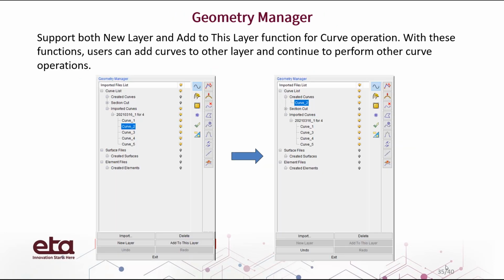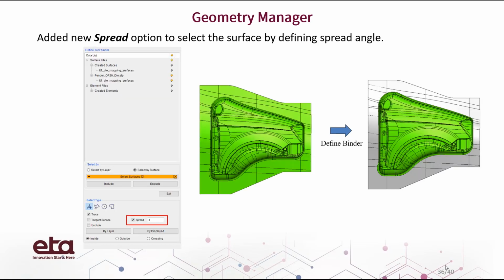A couple of enhancements are implemented in Geometry Manager. Here, the new layer and add to this layer functions are implemented in curve operation. It enables us to edit the imported curves. The spread option is implemented in surface selection. We can define spread angle to select surfaces.